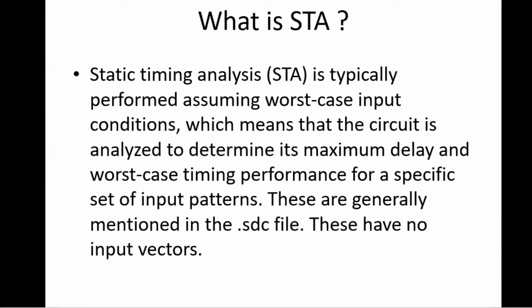And why do we do SS corner analysis for setup? Just make note of it. In setup analysis, we are delaying the combinational data.